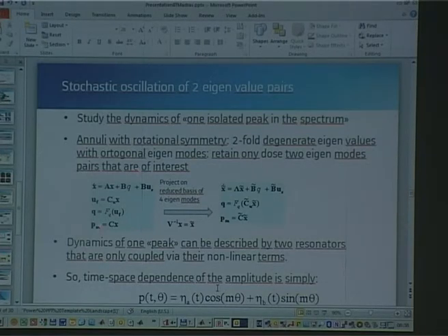And then from the state space analysis, I will not go into detail. You have a very elegant way of going from the full model to a very strongly reduced model, basically by calculating the eigenmodes of the system, and then projecting this large state vector only on the eigenmodes you're interested in. And these are just these 4 eigenmodes.